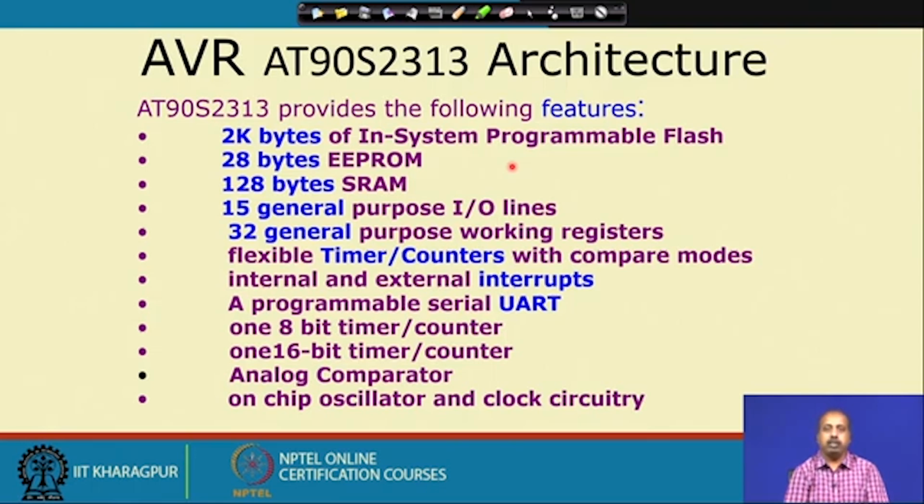So, what we have to do is convert those analog values into digital by means of some analog to digital converter, and then using that converter we have to run the program. So, we have to compare at the digital level. But if we can do it at the analog level itself, then these additional AD converters are not necessary. So, we can have this analog comparator in the AVR architecture.